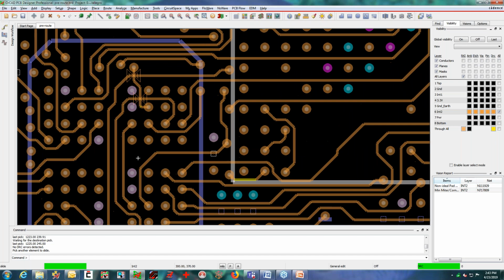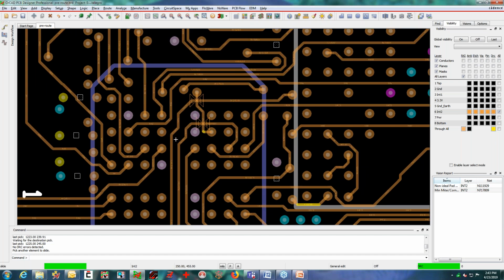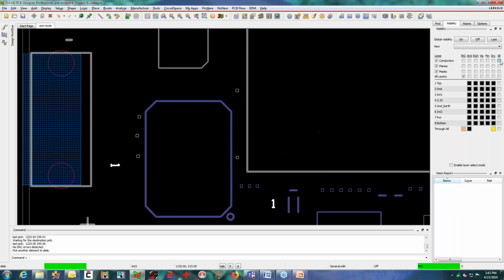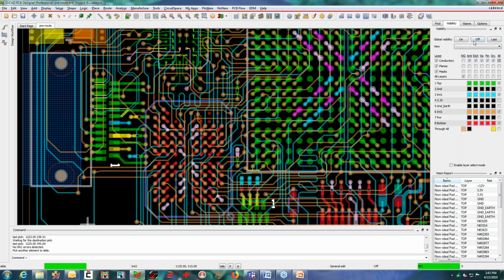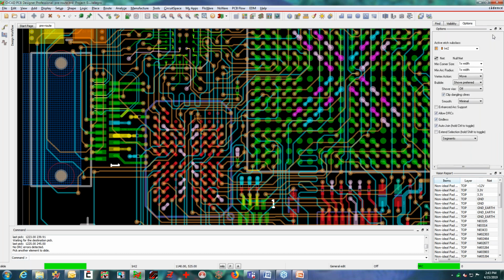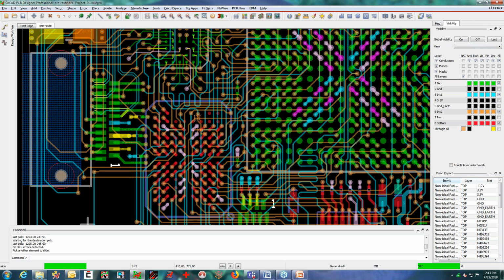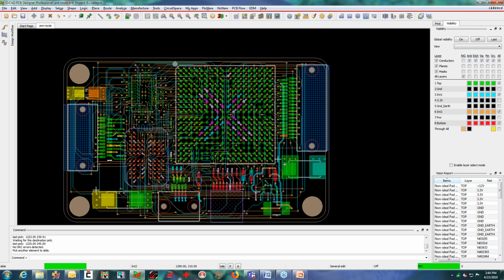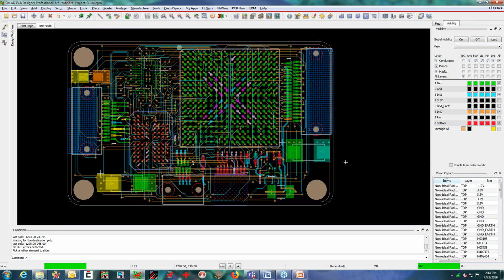But it looks like possibly my clock line may have blocked the channel down here. So these are things that you can evaluate. Once it's all complete, then you can start your manufacturing setup. And if it passes all your DFM checking, then you're good to go.